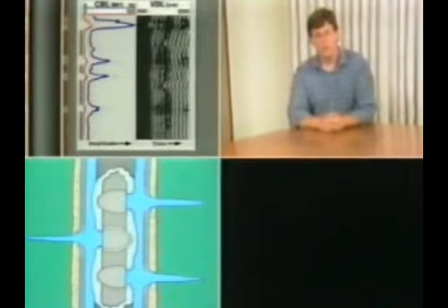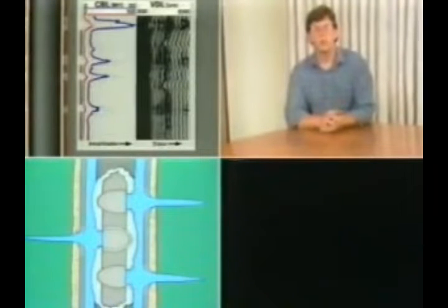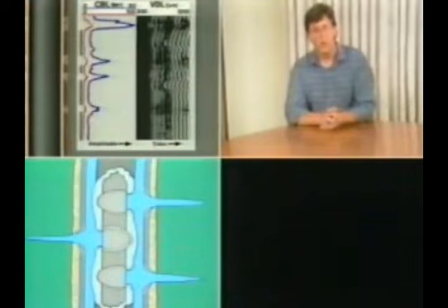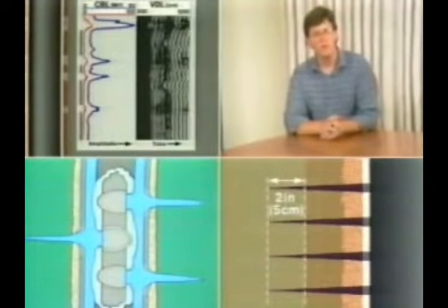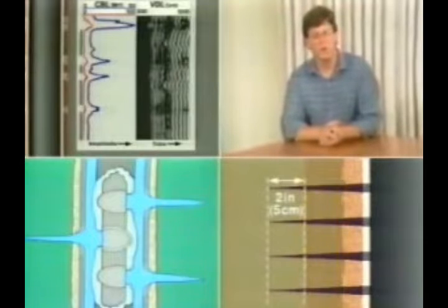the formation. Perforating is not just a matter of punching holes in the casing. If our well is to achieve its potential, those holes must be deep enough to reach past any formation damage caused by the drilling and cementing process. They must also be of sufficient number and arrangement to allow the formation fluids to flow into the wellbore unhindered. They must be unobstructed by mud or debris, and finally, they must be in the right position opposite the zones we have identified as productive prior to setting our casing.